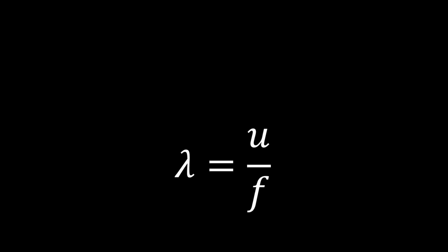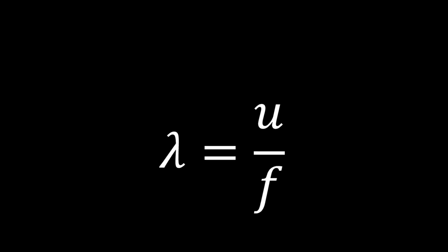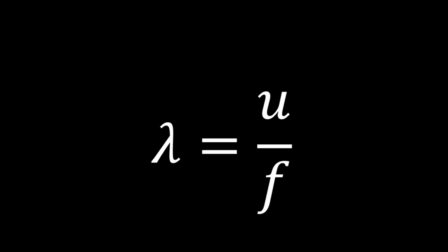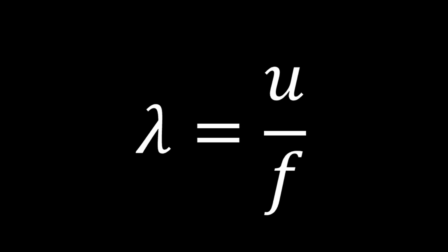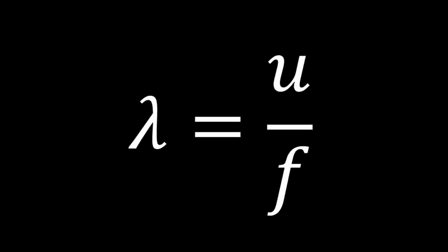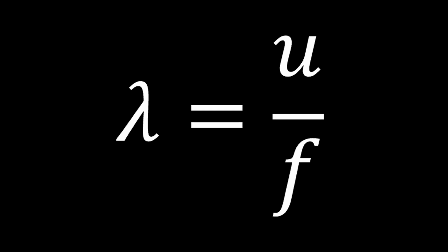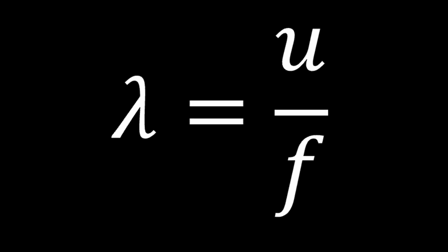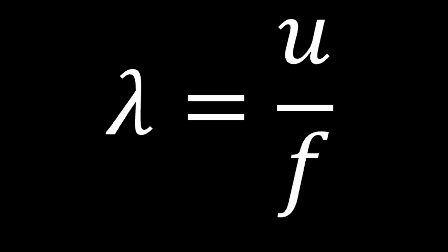A finite speed of propagation leads to a finite wavelength, and as frequency increases, the wavelength decreases. And as I said at the beginning of this session, when the length of a circuit element is a significant fraction of a wavelength, it will behave as a transmission line. So, here we are, and this will be another recurring theme going forward.